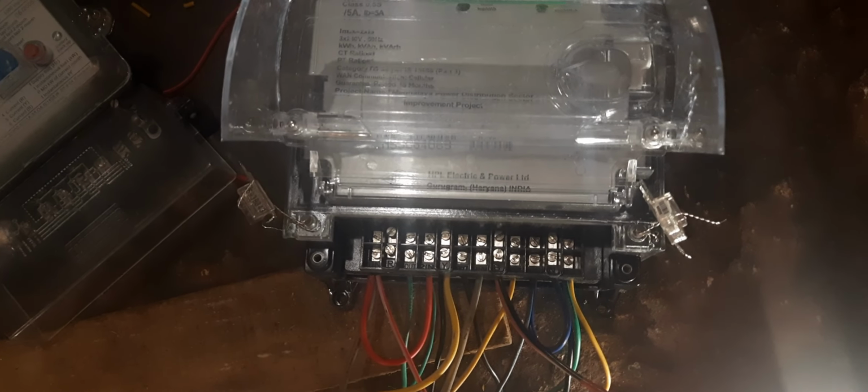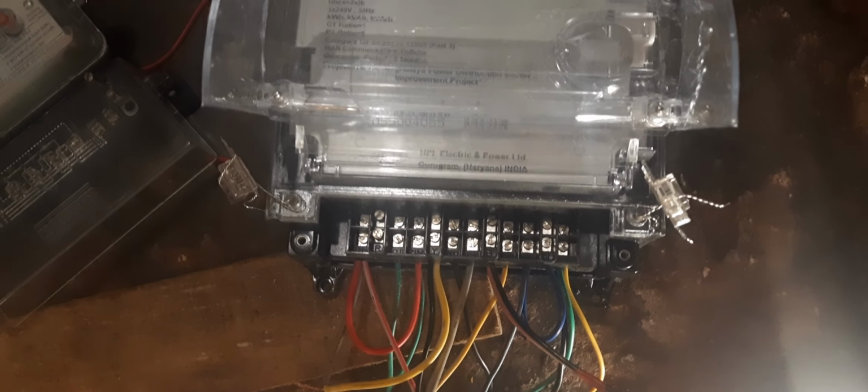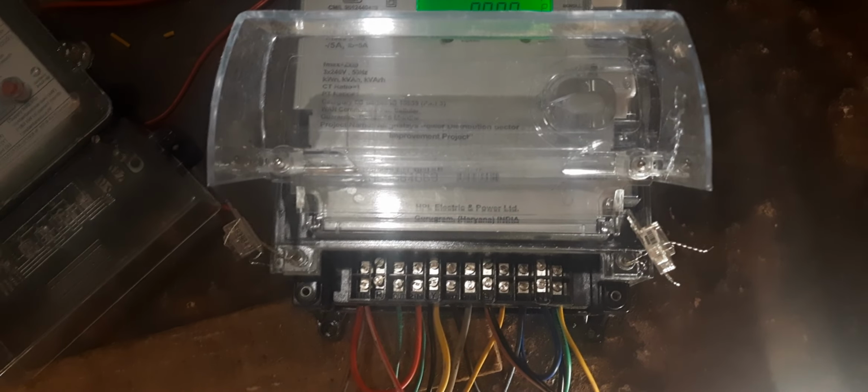So this is actually an LTCT meter, where I have given the connection like this. The PT supply, I have tapped from the phase only, because this is a domestic supply. For testing purposes, I have given a single phase supply to this meter. I have converted the single phase metering into a three phase metering, where in the R phase I have connected a heater, which is nothing but a 1000 watt heater, and the corresponding current, if you calculate, will be around 3.8, 3.9 ampere. And in the Y and B phases, I have connected a 7 watt bulb as a load.